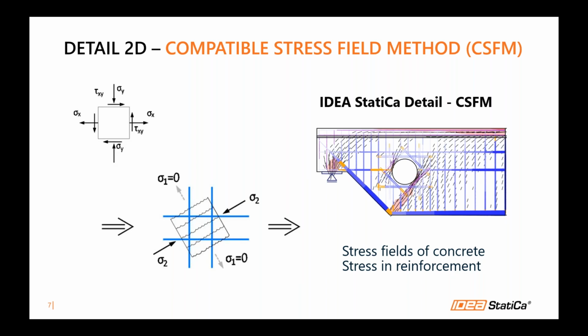The most important assumption is that the tension in concrete is neglected, and it's covered fully by reinforcement. So it follows that the solution is only suitable for reinforced concrete or reinforced concrete with pre-stressing. Also, this model is only for in-plane examples, so we have to simplify the examples into the plane and use only in-plane loading.